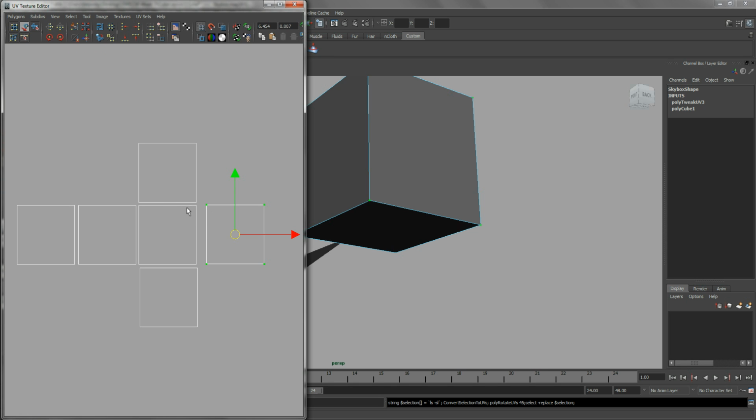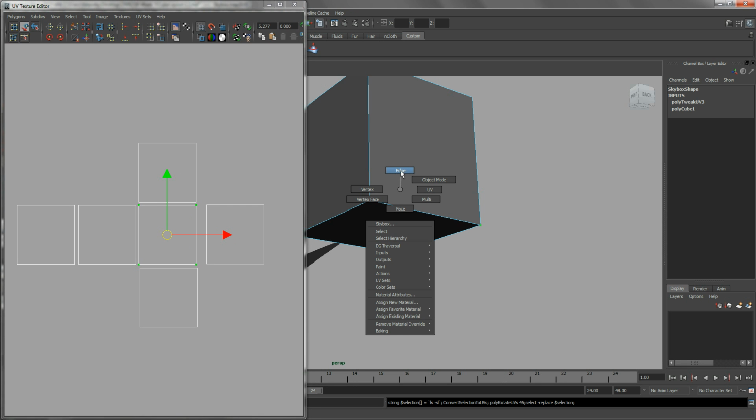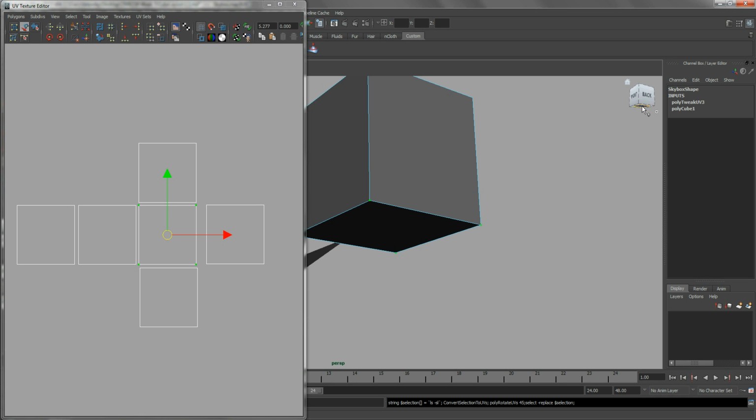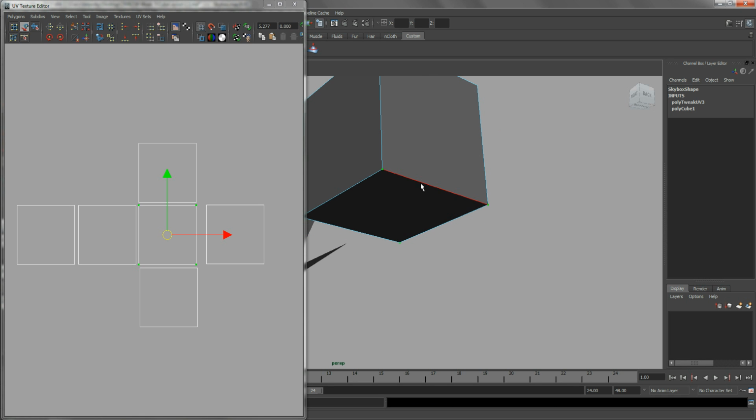Alright. So the next one is my bottom, and my bottom face, this edge should be facing that way. So I need to again rotate it. After doing the necessary rotations, I am going to select my edge again between my back and bottom to double check. So click on it, and now they are facing the right way. Okay, they are facing each other, so that is great. And we need to do it on the rest of the edges.